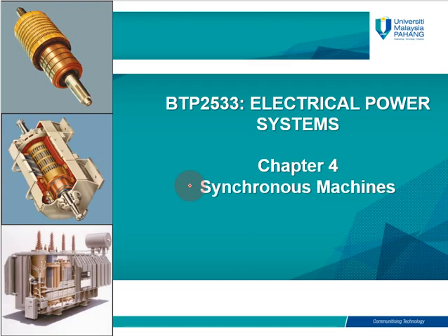That means the magnetic field of the synchronous machine is supplied from a separate DC power source, while in the induction machines, the magnetic field is produced by magnetic induction or transformer action, where the AC current is applied to the stator winding, it will induce magnetic flux rotating at synchronous speed, and this magnetic flux will cut or transfer to the rotor and cause the induction on the rotor windings.